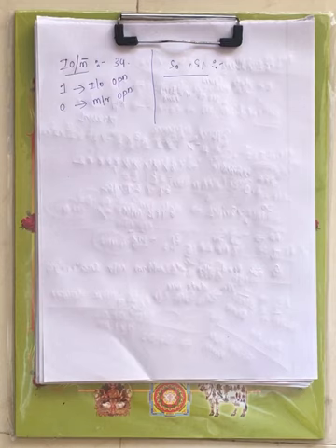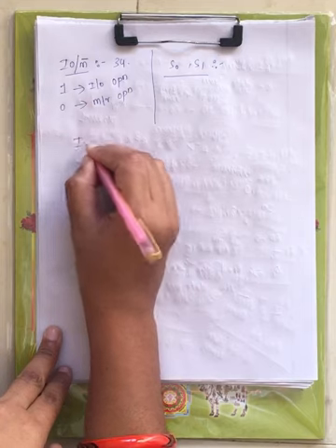Based on this IO/memory bar and S0 and S1, you have a table showing whether the microprocessor is performing a read operation, a write operation, or some other operation. That is decided by these signals. Now let me draw its table.